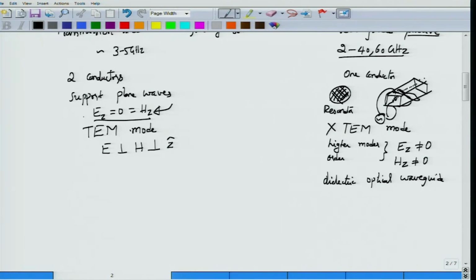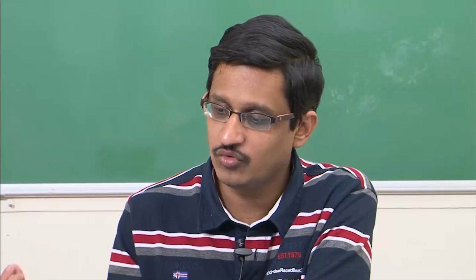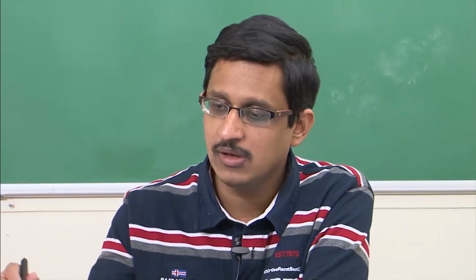Here energy is guided not in terms of gigahertz, energy is guided at terahertz. These are the corresponding frequencies for wavelengths which are around, say, 1550 nanometer, the most popular band for optical communication. So the corresponding frequencies are in terahertz, and they cannot use metallic conductors to conduct. You don't actually take a metallic hollow tube and shine light from one side and then expect light from the other side. You do get that, but for the kind of distance involved with a typical optical waveguide such as an optical fiber, you won't be able to obtain that from a conductor.